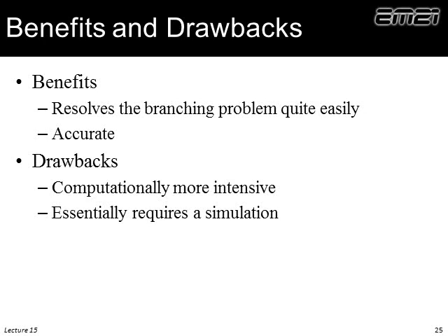A real neat thing about field averaging is that it doesn't involve any branching. We don't have to sort that out. It falls out of the mathematics automatically. It's a very accurate method. Drawbacks is it's rather computationally intensive, and I would say this really only applies to simulations. We can't go into the lab measuring scattering parameters and use this to retrieve our field values.